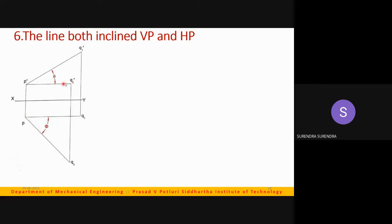Now, when the line is inclined to vertical plane, the true inclination and the true length is shown in top view. PQ is the true length in top view. P dash Q1 dash is the true length in front view. Similarly, PQ1 is the top view length. P dash Q2 dash is the front view length.